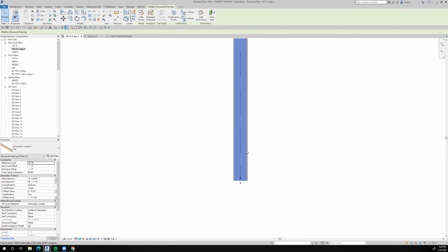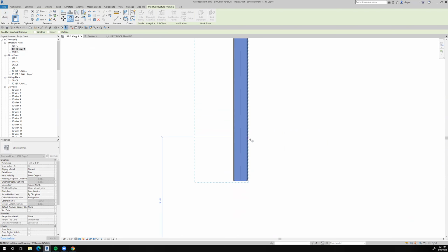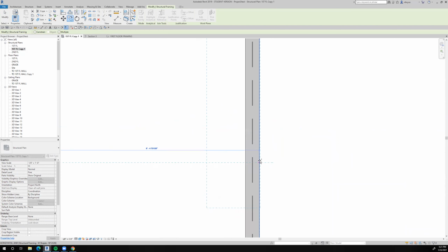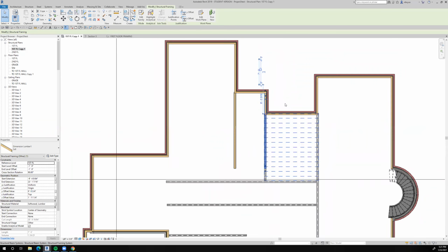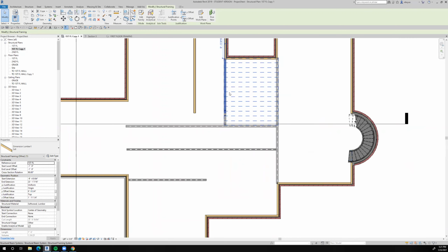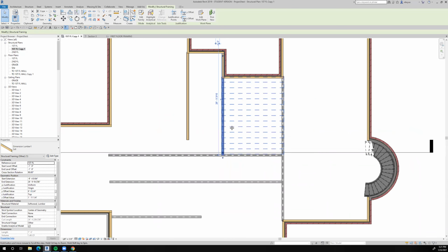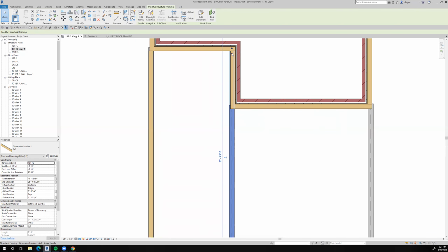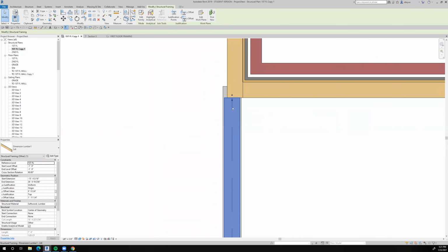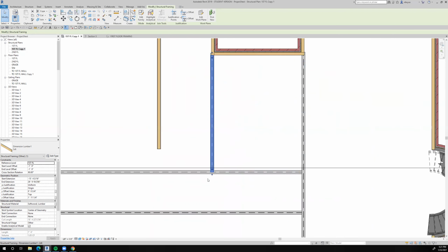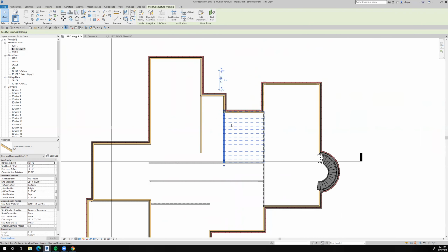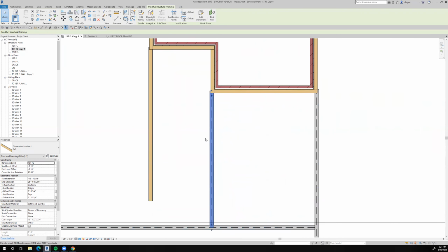I can copy it. Now I can copy it from the edge of the beam right there to the edge of this beam. It'll locate it in the same place. And let's stretch him down a little bit more. We want him to come across. Now that guy would actually come not as far as I've drawn it. I'll have to clean that up in a minute, but it wouldn't stop at the top of the beam. In this case, it would butt right up against the plate that I'm going to put across here.